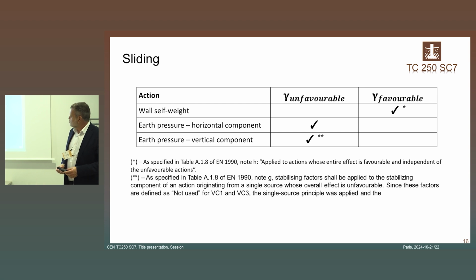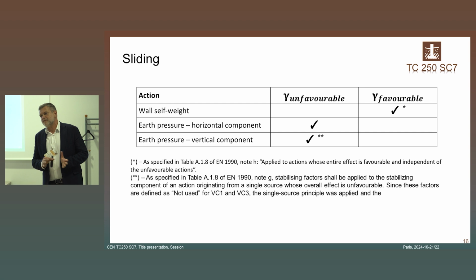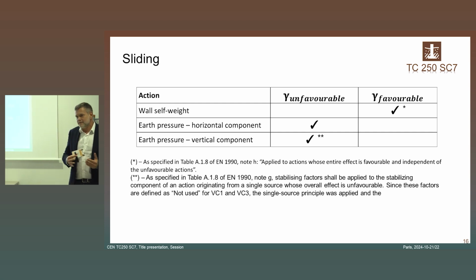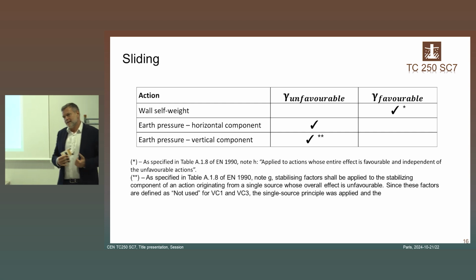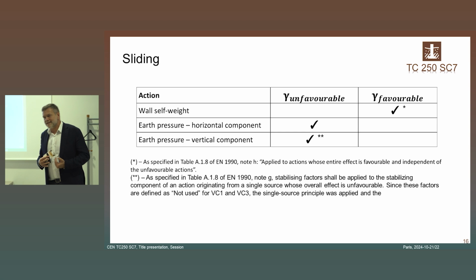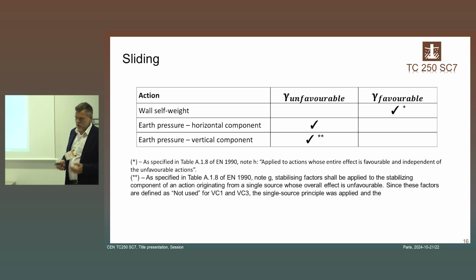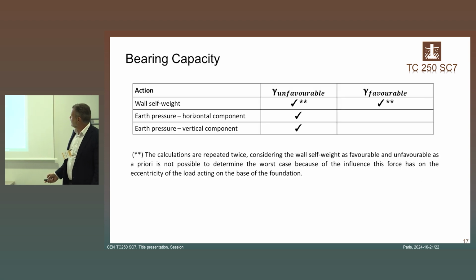And whenever we go to apply this for sliding, bearing capacity, and toppling, we have to consider which actions are favorable and unfavorable, always remembering that the components of the same action have to be treated homogeneously. So this is for sliding.